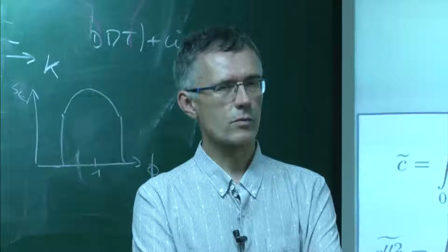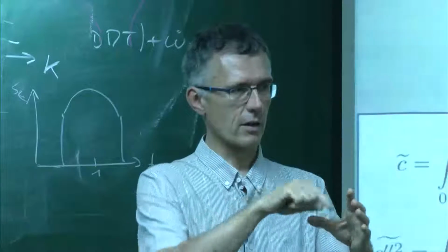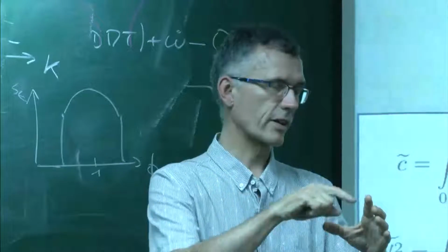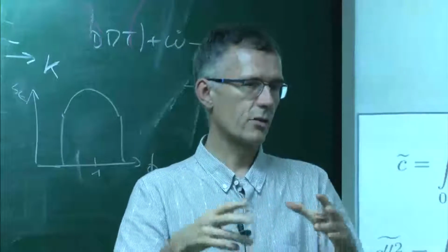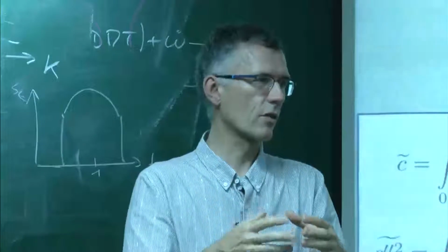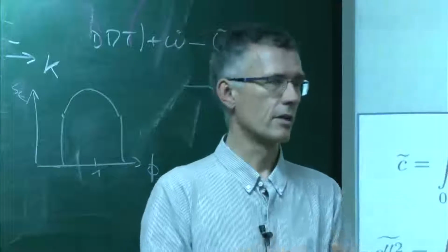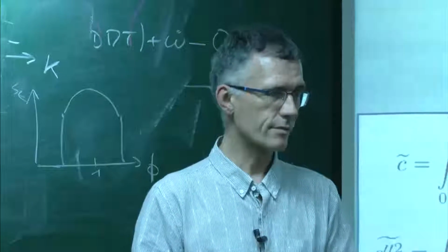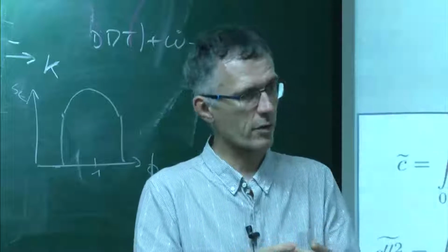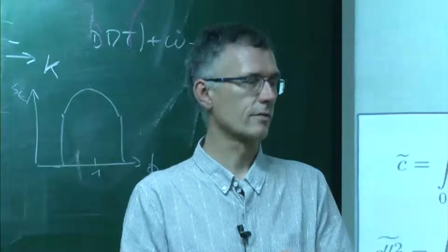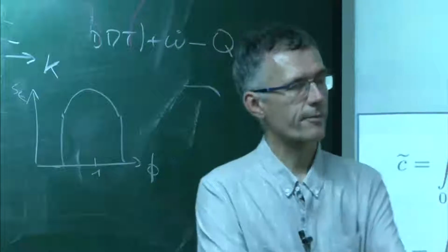Yes, well-stirred. When you do a well-stirred reactor, you don't do CFD. Actually, you just do a stochastic tracking of one particle in the reactor, and you do many of them, and you average all of them, and that gives you the result for the average quantity. But that's really a methodology which works only for the well-stirred reactor. You cannot do anything else with it because it works only if the flow is homogeneous, and you can only track particles in a Lagrangian way. But in a gas turbine, for example, you cannot do that.